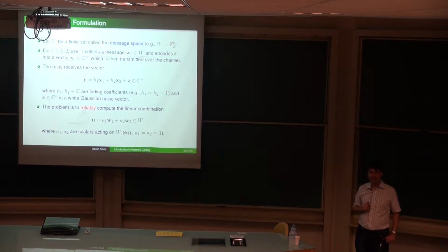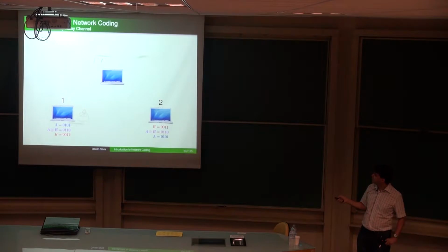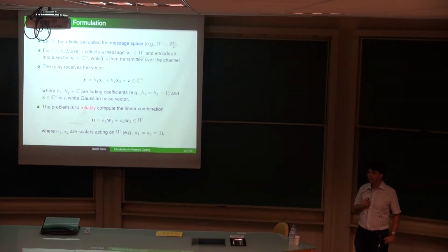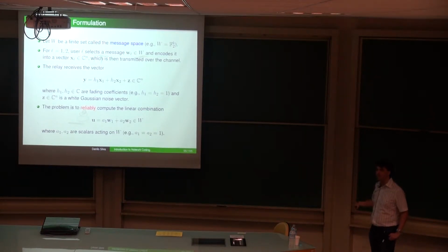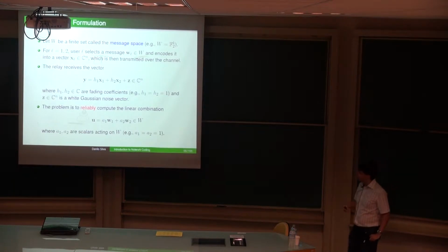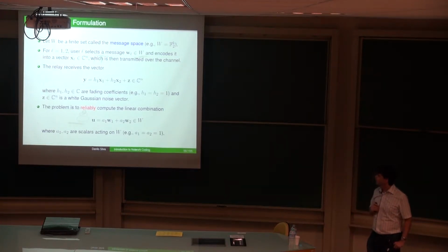So let me do one step back. Why vectors? Why do we have vectors? Aren't we transmitting signals? Waveforms? Why do we talk about vectors? I and Q. Sorry? I and Q. Can you elaborate a bit more? Imaginary part, real part, signals after going to baseband. Going to baseband, so that's the baseband equivalent model of a single carrier modulation, right? After matched filtering and sampling, so then we get a vector model.